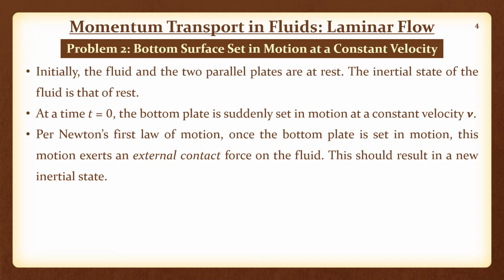And for this, we looked at in a previous lecture the model of a flowing fluid, that the Knudsen number should be less than 0.01, which basically means the mean free path for a molecule should be at least 100 times smaller than the characteristic length scale of the system. This basically means a fluid particle is typically of the order of at least a micron in size, and therefore it has hundreds and thousands of molecules inside that fluid particle, so that we need not consider the fluid as a discrete collection of molecules.